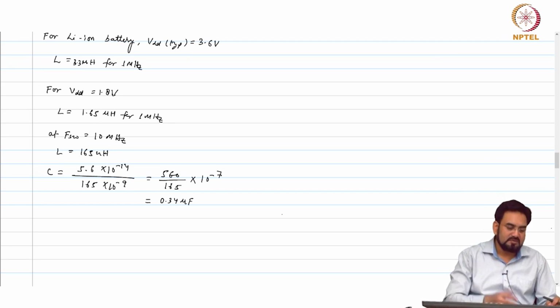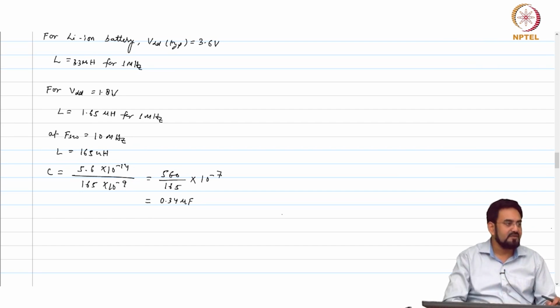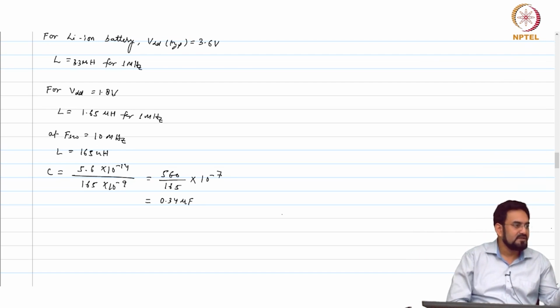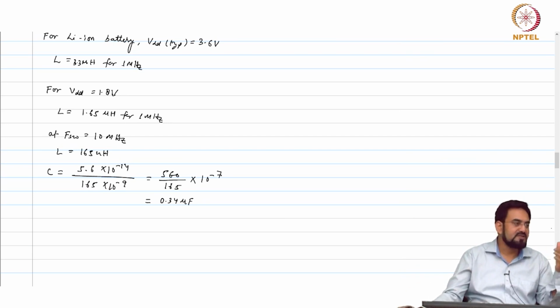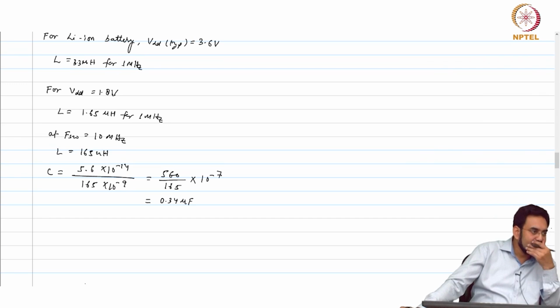So, let us say 1 amp current and you know the inductor value, which means you know the slope, correct. So, let us say for 50% duty cycle you are looking at 1.8 volt input and 0.9 output. So, what will be the slope? V in minus V out over L, 0.9 over L. How much is that?